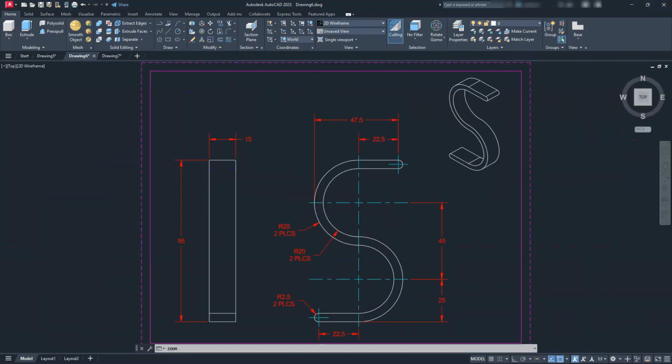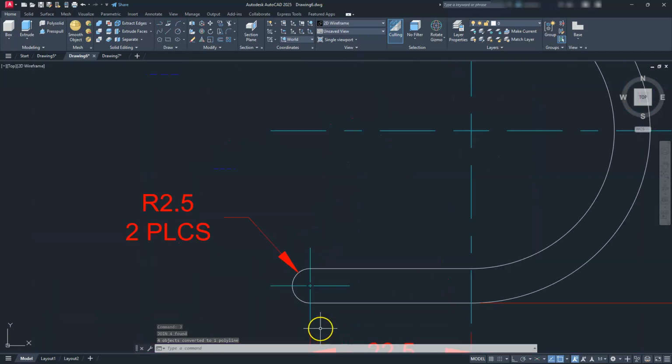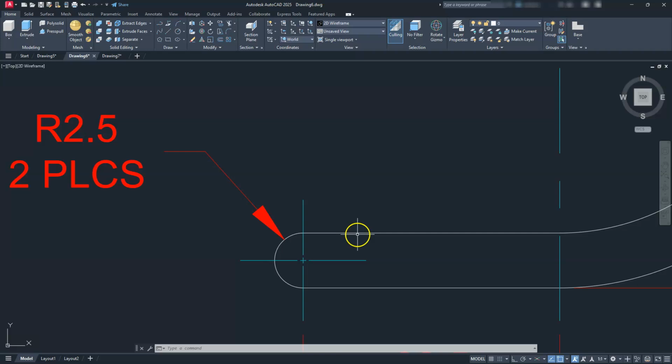And the way that we did that was we would create the shape here in 2D, and then just like I did before, by selecting these lines here to create that contour flange, or these lines that I would use to create that with, you would join these together, right? So I can select all of these and then I would join them together. You can see that they are one part. And then I would offset this, whatever the half of this is, right? So that's going to be 2.5.